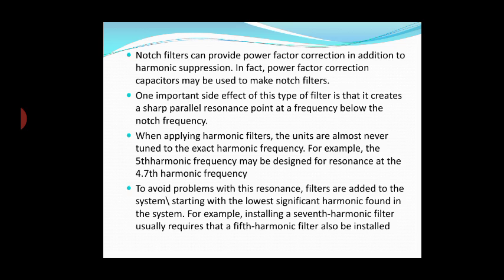When applying a harmonic filter, the units are almost never tuned to the exact harmonic frequency. For example, the fifth harmonic filter may be designed for a resonance at the 4.7th harmonic frequency.